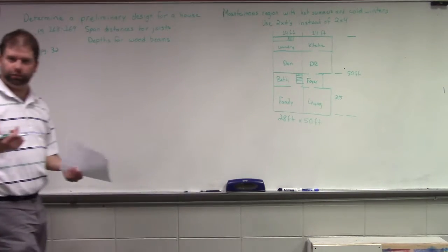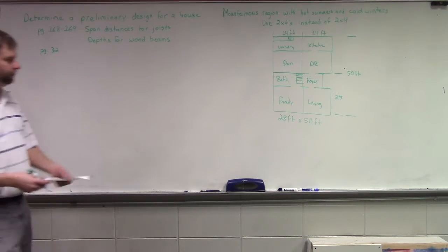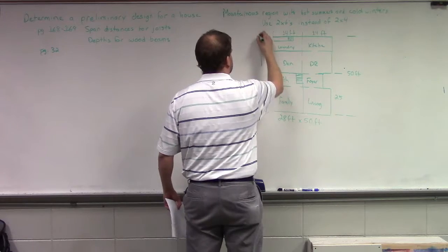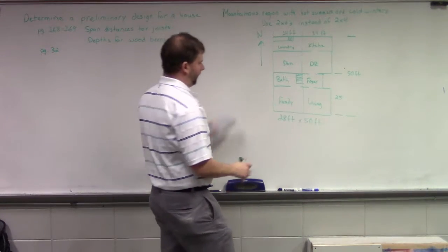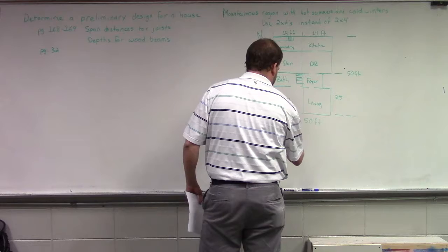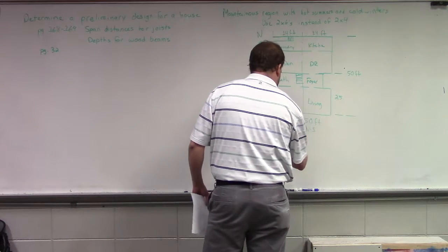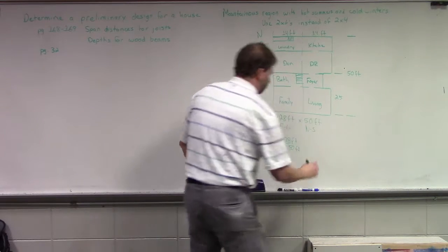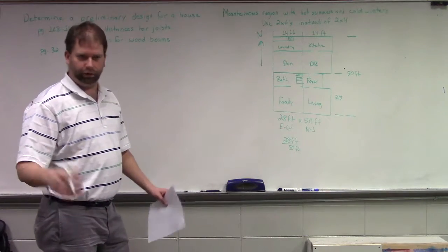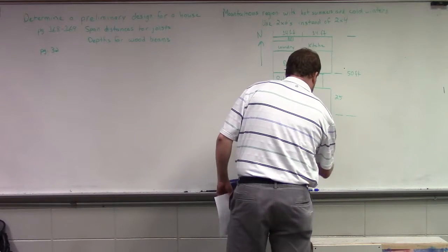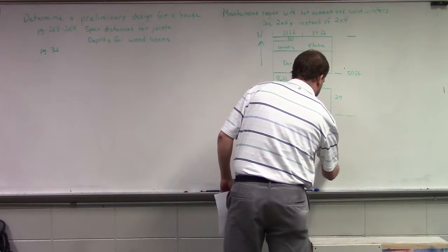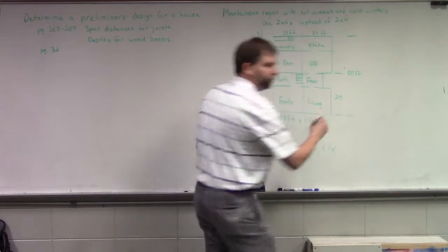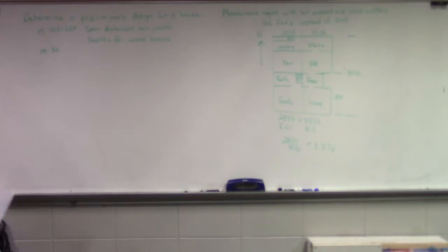Okay. And what's that ratio? 1 to 3, right? So all you need to do, you have 28 feet. Sorry, just for ease, we'll say that that's north. So 28 feet running east to west and 50 feet running north to south. That's less than 1 to 2. It's about 1.22, something like that. But less than 1 to 3, right? Yeah. So we're good. So we don't need any internal shear, okay?